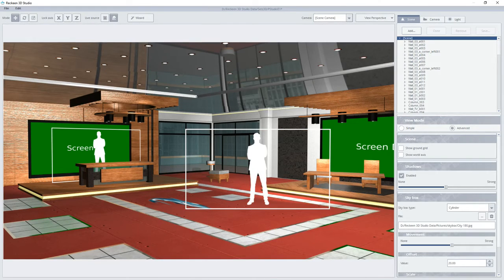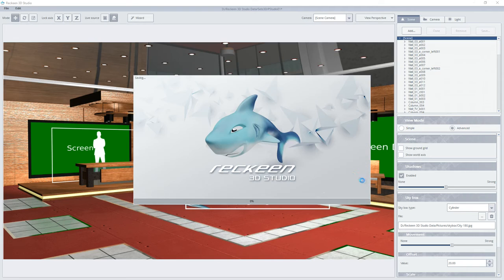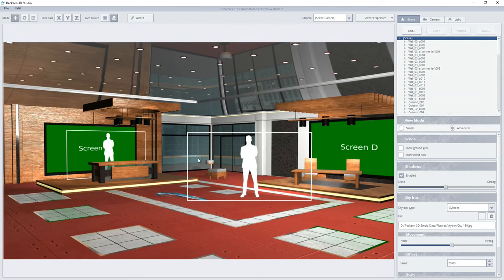Finally, such modified studio with elements added, shadows enabled, sources set up, a logo added, and with a material and a color changed, can be freely saved as a new studio file. We choose File, Save Studio As. We enter a file name. We save it. Such project can be loaded into 3D production module.